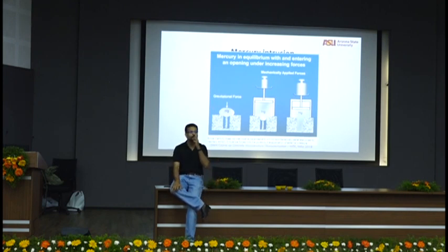That is why in nature, simple example, you put this big 100-story, 50-story building on a rock. You take the rock and test the uniaxial strength of the rock. Can it carry this entire building? Why is it not failing? The rock is confined from all the sides by everything else. The substrata in which you're building this big building is confined triaxially.